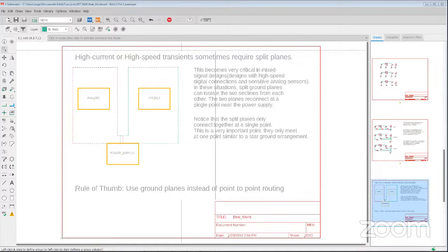You can do that, and that does work. I think mentally it's a bit more taxing, but it is the most ideal way. If you can maintain the continuous plane, that's preferable to having to do split planes, because now you don't have as low an impedance to that reference plane. But they're considered about equivalent, although it's slightly better to have a continuous plane.